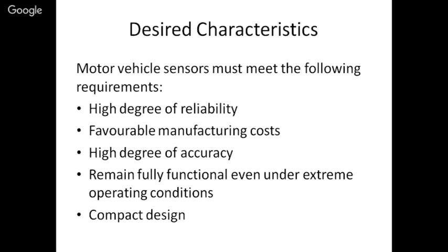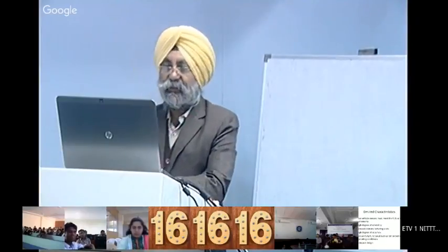So to reduce the effort or to maintain the same deceleration of all the four wheels, the injectors that inject the oil into the braking cylinders work at a frequency of say 1000 hertz. In 1 second they will open and close 1000 times. So you can see how much high accuracy is required.